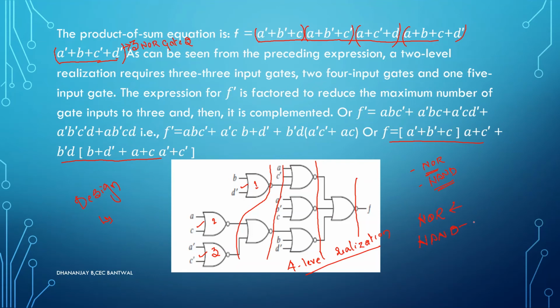You know why this is possible? Because both these gates are universal gates. What you used to do was, you would have rigged up the circuit using basic gates. Now what you need to do is, you need to replace these basic gates by NAND or NOR gates. This is possible. But a circuit design using the limited gate fan-in, most of the times it is difficult. Until and unless you are a pro in this particular procedure, you can go with this. Beyond that, it is not possible.